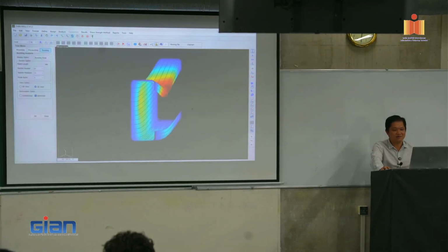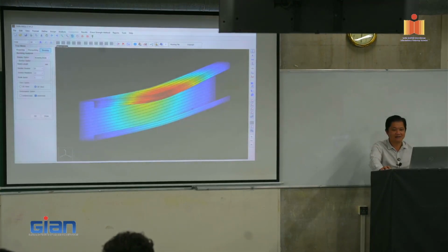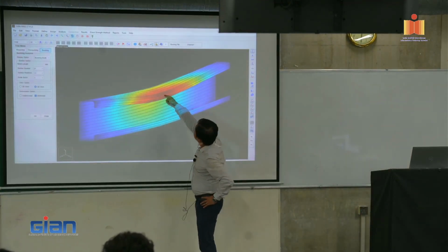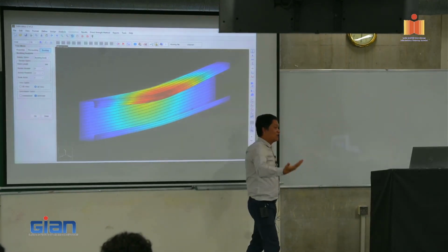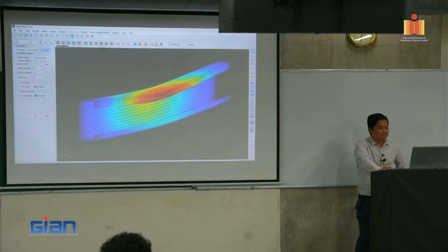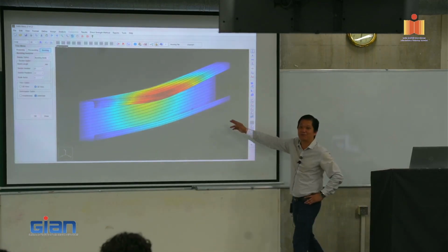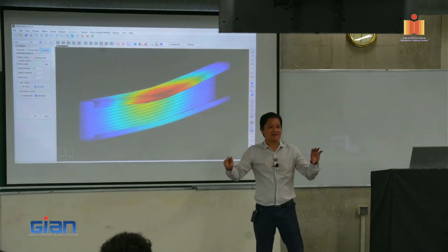Okay, you can see that if you're pushing one end, at the end it's localized in here, right here. You can see that a lot of localized in here. So that allows you to do analysis on that based on finite strip method, and you can push down. Right. So you might ask me what we need to do with this one, and what this is part of: the direct strength method for localized loading we're developing now. So this is part of the pre-critical that you need. And then another one, we have to develop the direct strength equation.